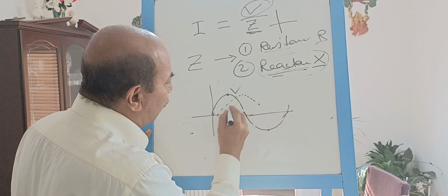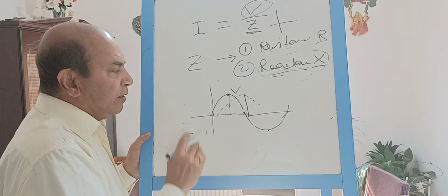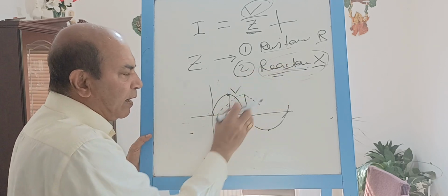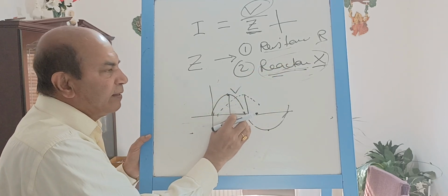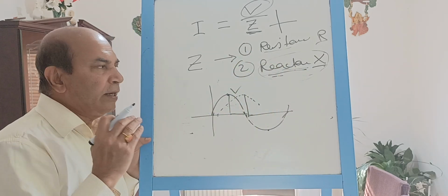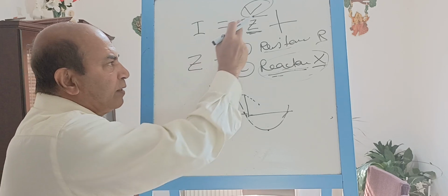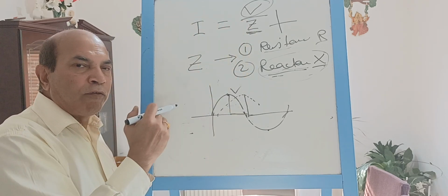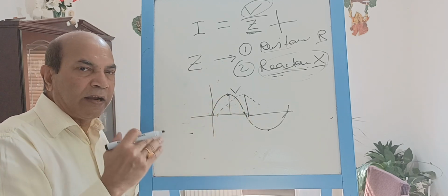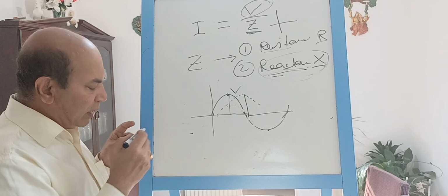You see there, when the voltage is at a peak, the current peaks after some time. So there is a time difference. This phase difference, or lagging, in the case of inductive current, we call lagging. The lagging is introduced due to the reactance of the circuit. That means indirectly we can say the reactance of a circuit has two properties. One property is to oppose the flowing of the current. The second property is that the reactance causes the current flowing in the circuit to be out of phase with the voltage. So this is the reactance.